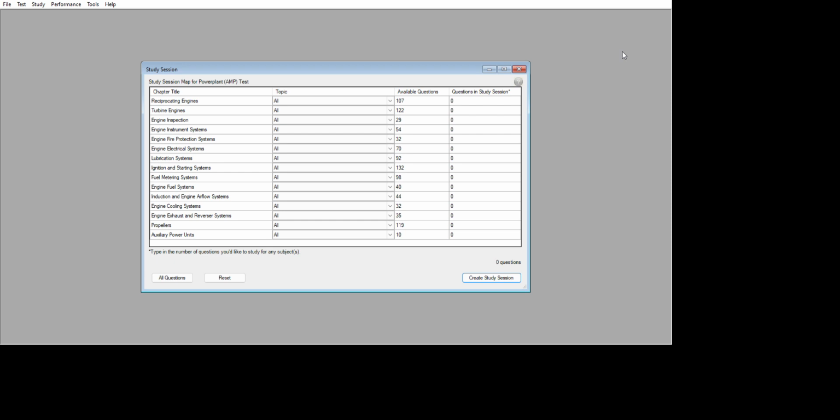An increase in the cylinder head temperature. What effect does a high atmospheric humidity have on the operation of the jet engine? Little or no effect. Using cool spark plugs in a high compression aircraft engine would probably result in normal operation. So cold spark plugs are used in the high compression aircraft engine.